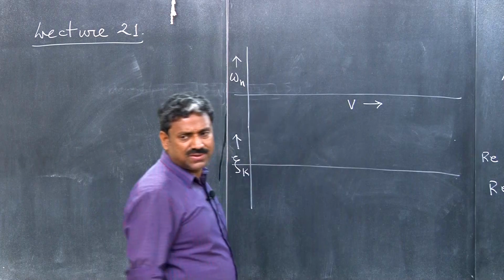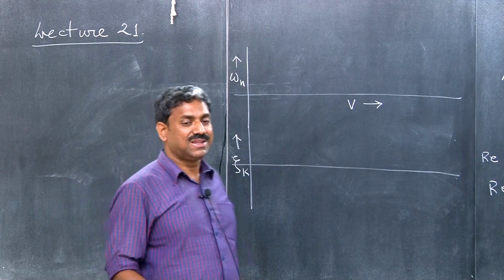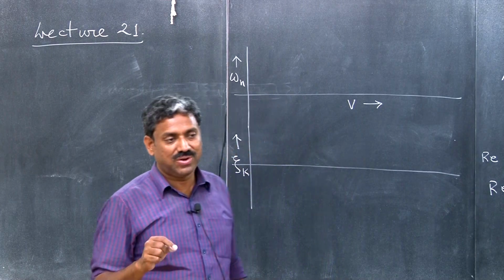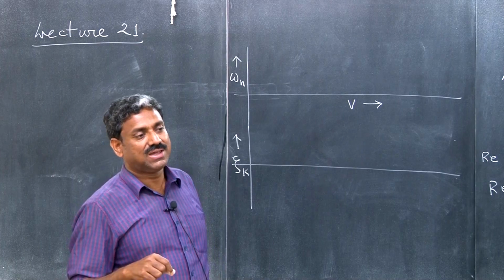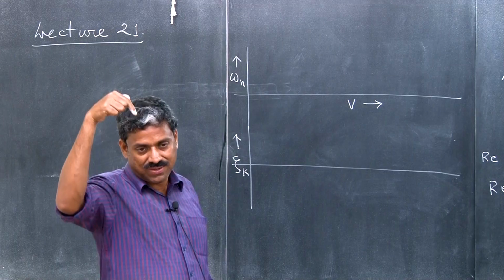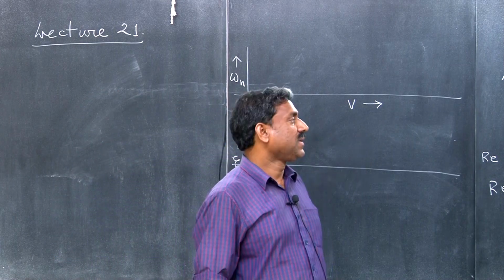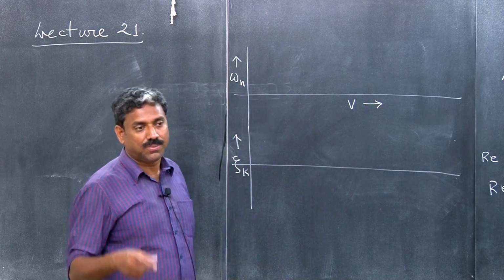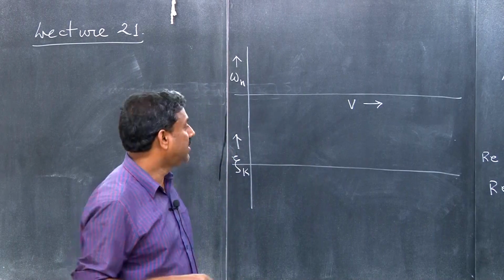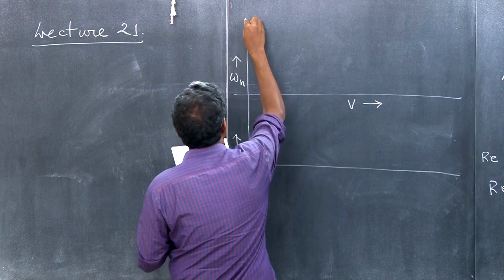I am assuming that this is for aerodynamic instability, so wind velocity V, but not necessarily that you have to consider this wind velocity. This can be any parameter which is controlling the stability. It can be destabilizing wind speed, it can be for gyroscopic motion, it can be axial force P for the rotating shaft, for parametric resonance it can of course be the dynamic component of P. So here I have shown you how this plot looks.